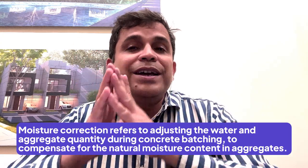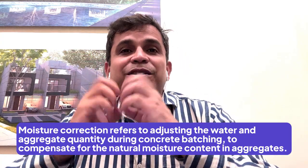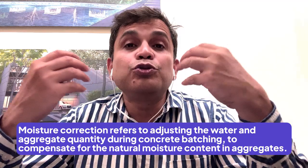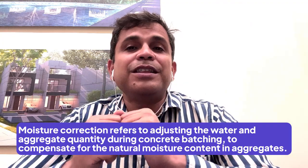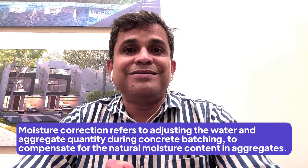Now the coarse aggregate and the fine aggregate have the property that they retain moisture. If they are retaining moisture, whenever we are adding water into the mix, this moisture can be released to the mix and the water cement ratio will increase. And if the water cement ratio is increased, what will happen? We will not get the desired strength. Our strength and durability will be in a problem. So this moisture has to be calculated. Otherwise the mix proportion we have already decided will not be the same one. So that is why it is extremely important to adjust the moisture correction.